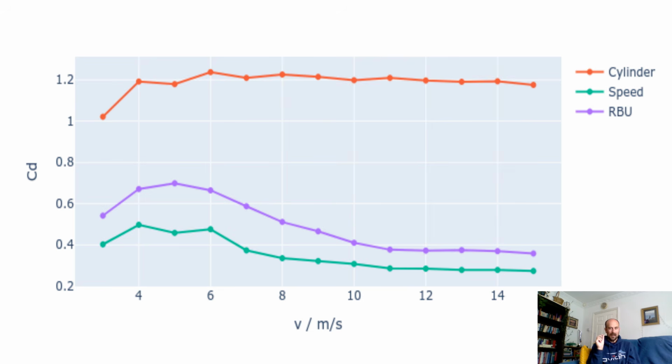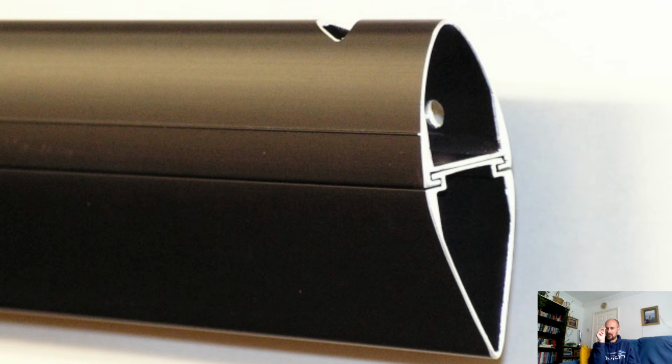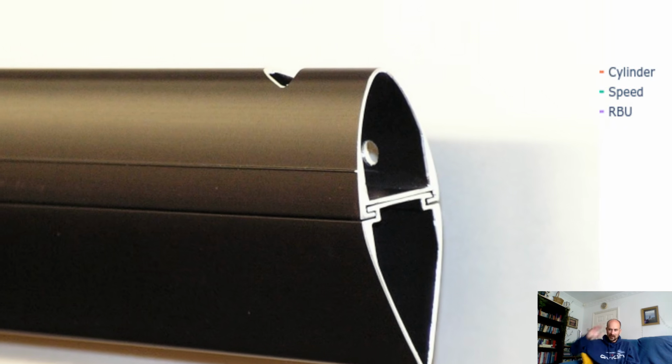I think what's happening there is it's showing that those turbulators, those tiny little strips, if you look along the front of your uprights, if you've got aerofoil uprights, look along them and you'll see these tiny little ridges. They're not very high, but what they're doing is they're tripping the airflow. So as you start to increase the speed, at the very low speeds, now it's very difficult to measure down this low, but you'll get a smooth flow around the shape.